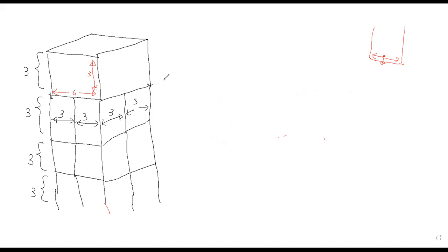You will see, so this is Z equals 9 and this is Z equals 12, right? So SAP usually assigns the pressure by a joint pattern. So it has something like AX + BY + CZ + D, right?